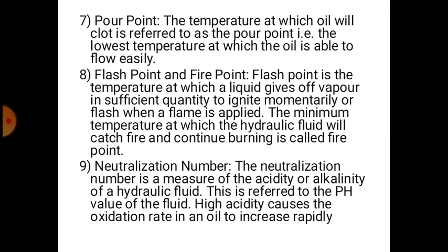Flash point and fire point. The flash point is the temperature at which a liquid gives off vapor in sufficient quantity to ignite momentarily. So momentarily it will ignite, or flashes are formed, when a flame is applied. At what temperature will the hydraulic fluid catch fire? The minimum temperature at which the hydraulic fluid will catch fire and continue burning is called the fire point.